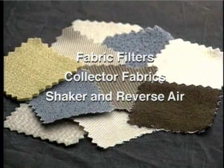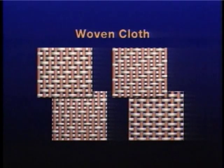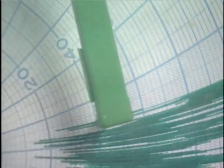The fabric used in shaker and reverse air collectors is usually a lightweight woven fiber material. The fiber that is used is chosen based on the abrasive characteristics of the particles, the chemical characteristics of the particles in the gas stream, and the temperature of the gas stream. The openings in the fabric weave are about 20 to 60 micrometers.